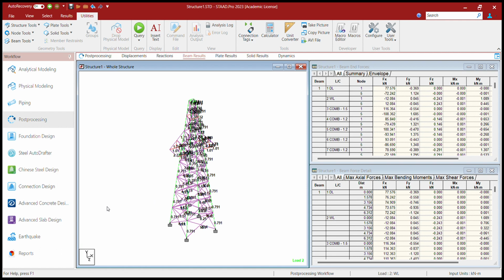And steel takeoff gives you the total quantity, that is the two properties that we have, that is short leg back to back ISA section 200 by 150 by 15. Total length is 201 and weight is 156, and the next one is given. In member takeoff you get it as per the member. Okay, so here it is completed.